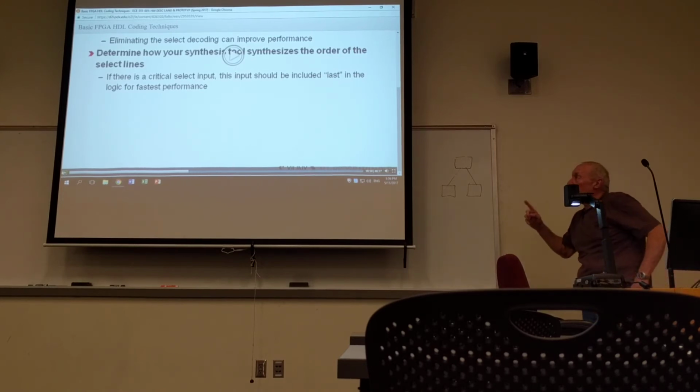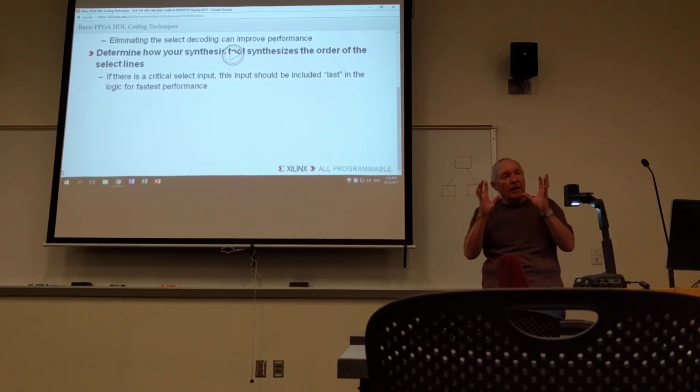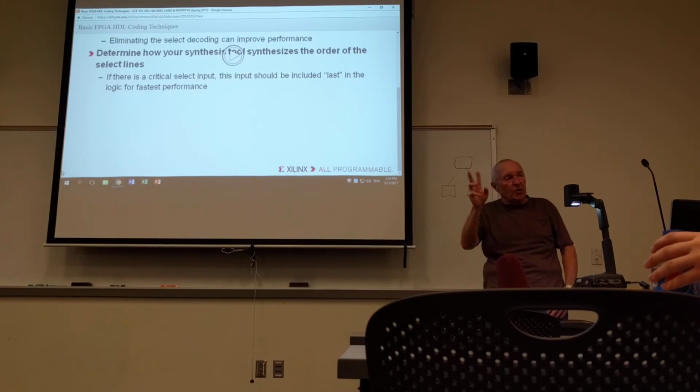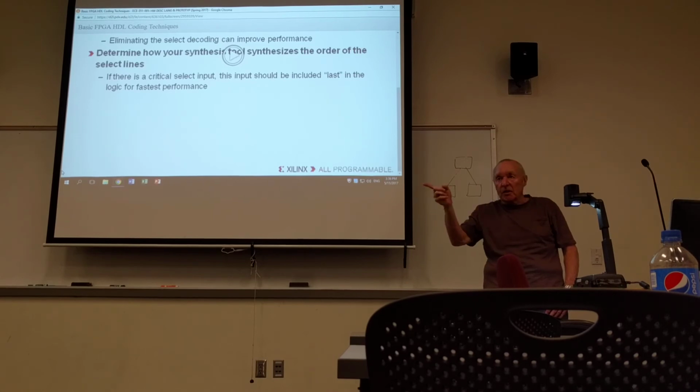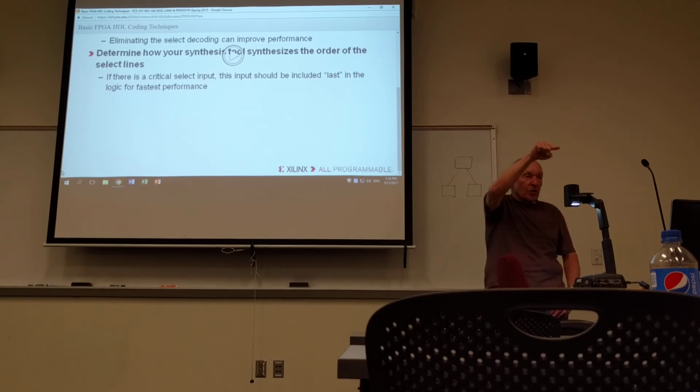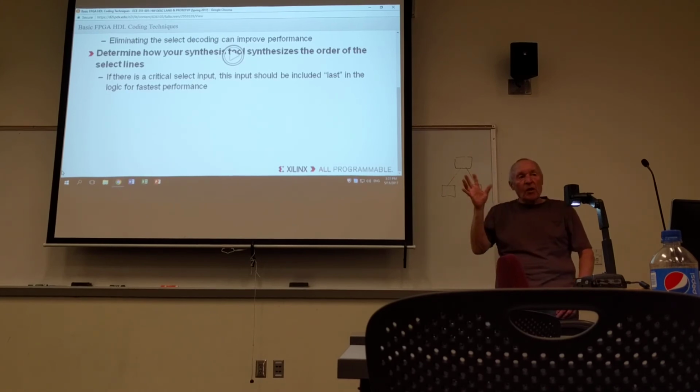So what he means by doing that is, let's suppose I have a 4-to-1 MUX. I would need 2 select lines, and depending on 0, 0, 0, 1, 1, 0, or 1, 1 on those select lines, determines which of the 4 inputs gets hooked to the output. If you use one-hot encoding instead of 2 select lines, you have 4 select lines. And so all of the select lines are 0 except one of them. And that's the one that determines which output you have. So you have a select line corresponding to each input that you have. That's the one-hot encoding of the select lines.